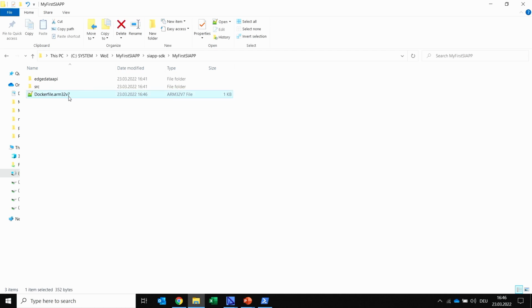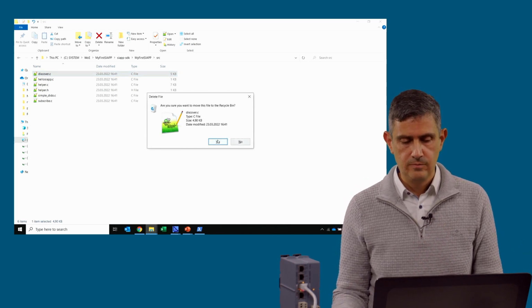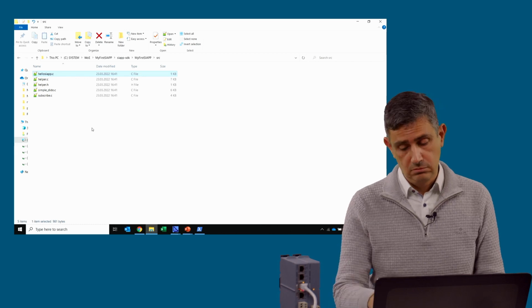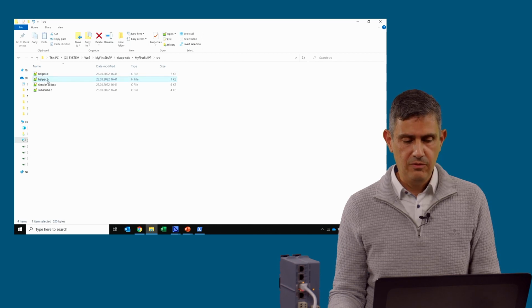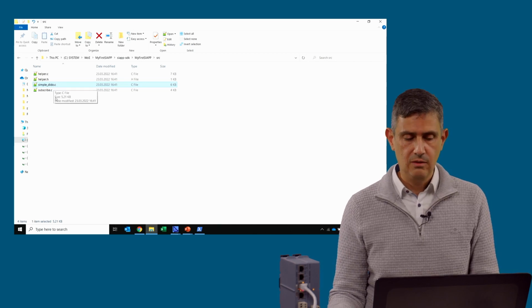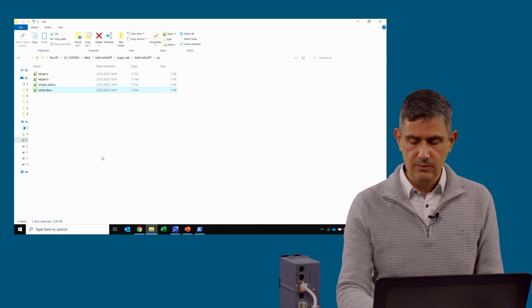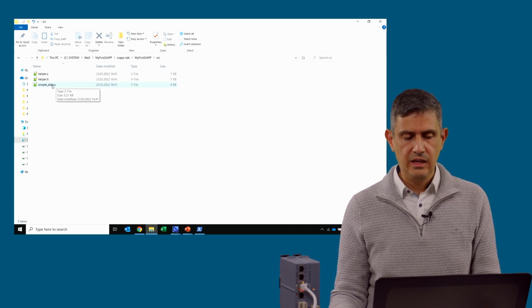Now we should go to where we write the code. So let's go to SRC. Here we see a lot of program codes, one for this discover program, which we just erased from the instructions, so we can just remove it. Hello SIAPP, nice to have, but we are not using it, so erase it. These two we will leave because they are actually called from the simple DIDO, we will see where. And this subscribe we are not using, so remove. So far we have only this simple DIDO.